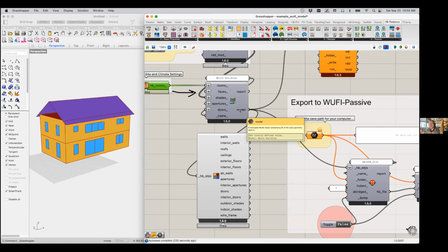You then pass that model off to whatever calculator you want to use for whatever it is that you're investigating. Could be passive house certification, could be daylighting, could be thermal comfort, could be hourly energy, could be carbon emissions assessment. So that's exactly right. We're just building up this model, but this model is software agnostic, calculator agnostic. It is just a description of the building. We can then use that to do whatever we want to it.